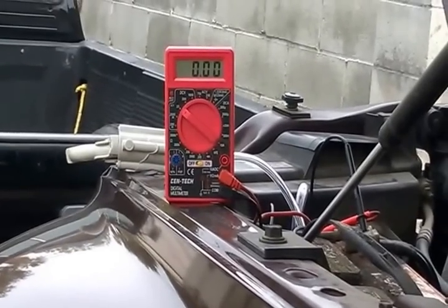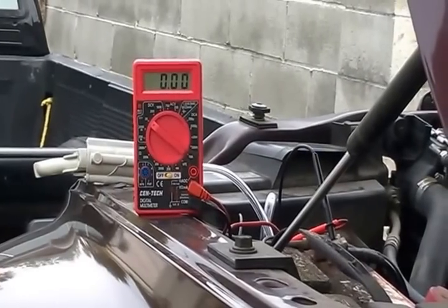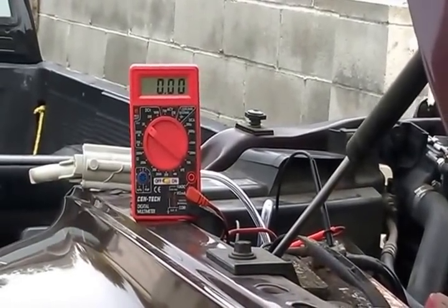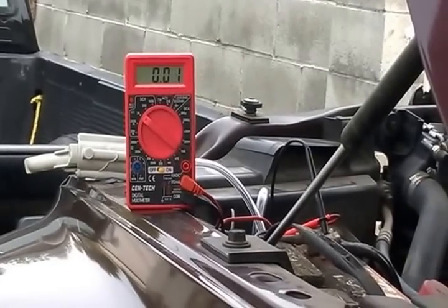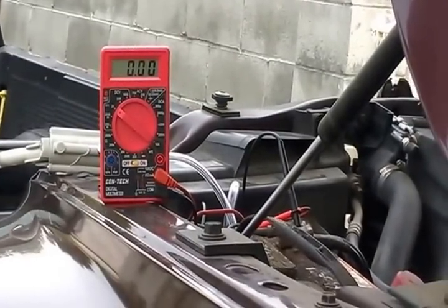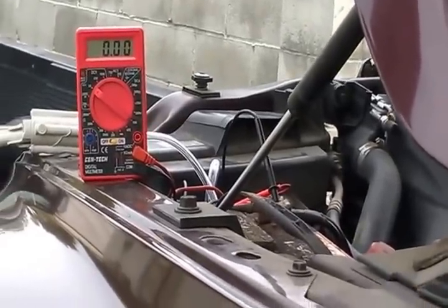As you can see, the scan tool already commanded this pulse width modulation voltage, which was varying. I'm gonna hit it one more time. As you can see, it's varying right there. The high was 5.56. So it's basically the same voltage as the other solenoid.